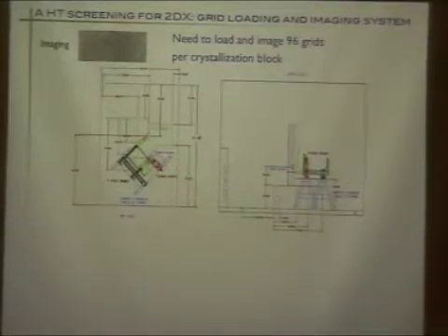The robot has a suction device. The robot goes and picks up the grid by suction from the platform. It has a laser. It knows whether the grid has been loaded or not. And then this pivotal SCARA robot transfers the grid to this other black robot, the Cartesian robot, which holds a stage, and then this robot goes and inserts the stage into the microscope.